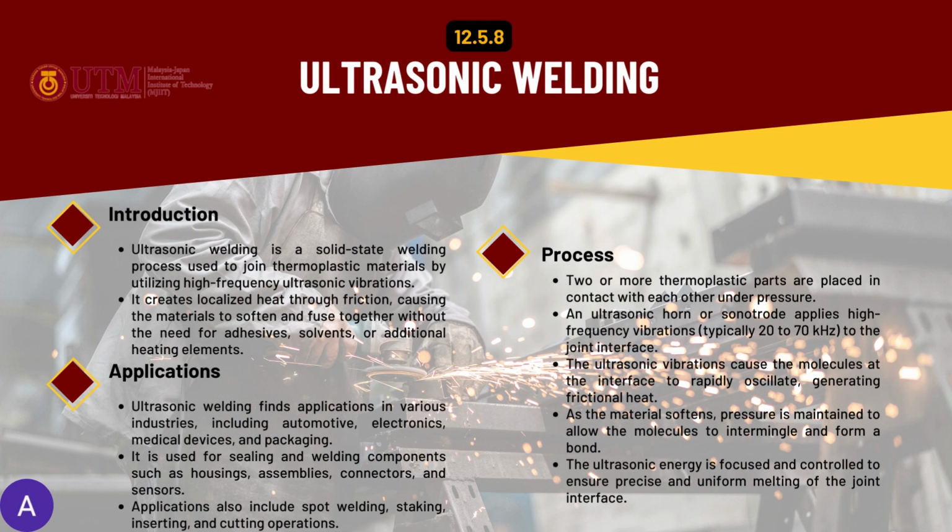The last one is ultrasonic welding. Ultrasonic welding is a solid-state welding process used to join thermoplastic materials by utilizing high-frequency ultrasonic vibration. It creates localized heat through friction, causing the material to soften and fuse together without the need for adhesive.